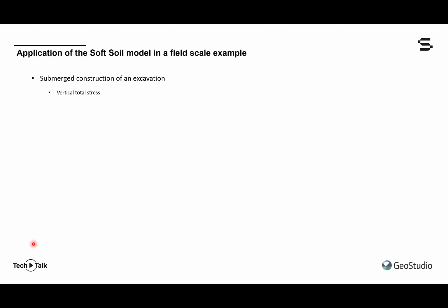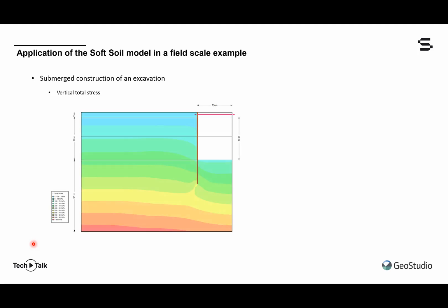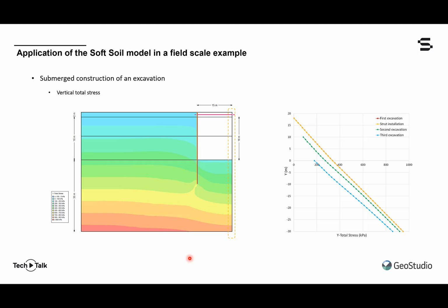And so I'll let you explore exactly how that was done. It is quite intuitive. You can explore that in the actual project file on our website. In the next few slides, I just want to very quickly examine some of the things you can explore in these types of simulations. The first is the stress distribution of vertical total stress as a result of submerged excavation. And so this is a plot along the center line right here, showing those total stress profiles at all phases. There's some overlap in this figure.